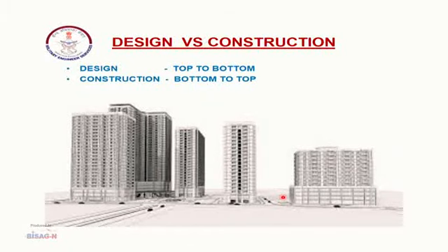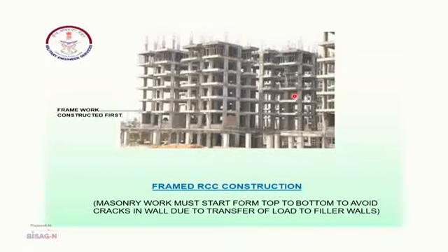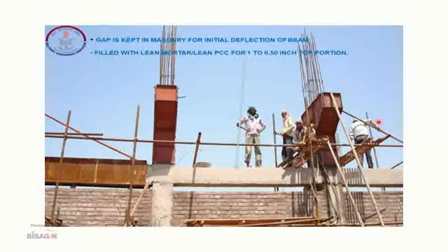So, here I want to stress that when a designer starts the design of the building, design starts from the roof and goes towards the foundation, but construction starts from the bottom and goes upwards. So, as per standard practice, the designer thinks that the entire framework will be constructed first and then loading will start from top, but practically it does not happen at site because of the contractor's easiness, so that progress can be achieved. So, there are methods to achieve this.